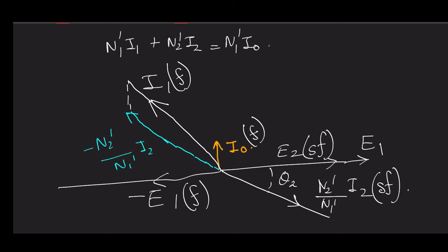During run, the way we have defined it, slip is less than 1. In motoring mode, slip has this value. And once slip is less than 1, then the frequency of your rotor induced EMF and current flowing through it are not the same as the stator current flowing through the stator winding or stator induced EMF, isn't it? So what is the mistake we have made here?